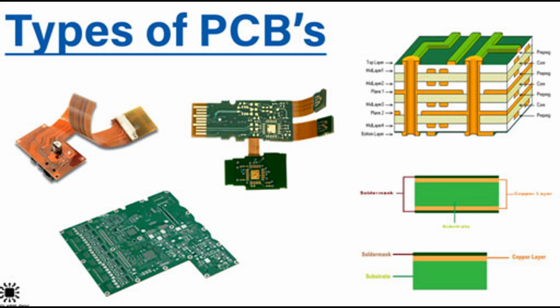Thermal management. Substrates can influence the thermal properties of the PCB. Certain substrates may have better or worse heat dissipating properties, which can impact the PCB's ability to manage and dissipate heat generated by electronic components. Common materials used as substrates for PCBs include FR4, flame retardant 4.